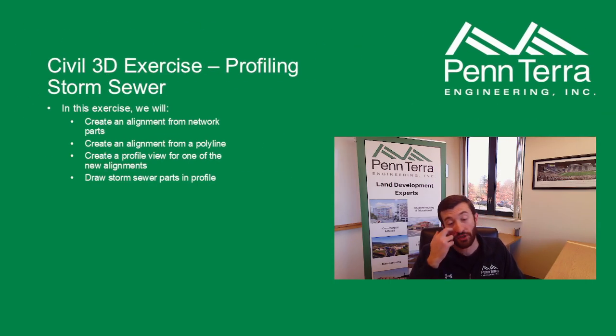So we're going to jump over to Civil 3D and do an exercise for profiling storm sewer, in which we are going to create an alignment from network parts. We're also going to create an alignment from a polyline. Then we're going to create a profile view for one of those new alignments and draw some storm sewer parts within that profile.